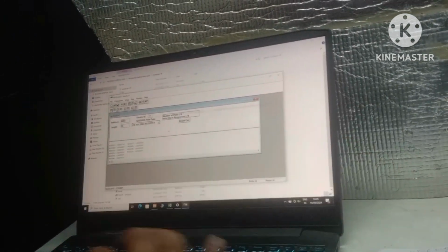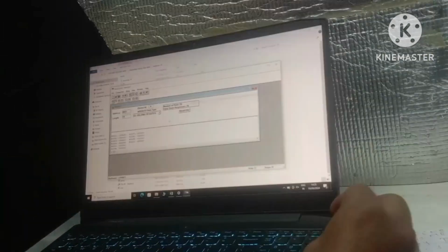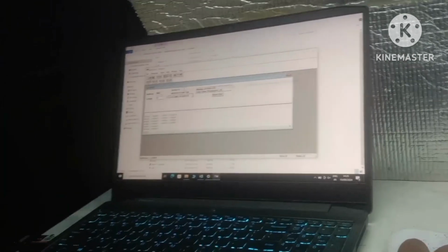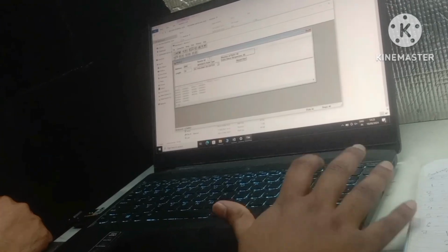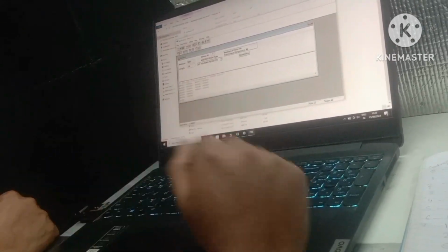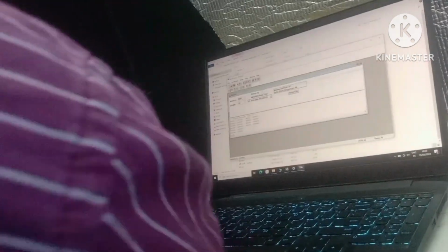If we have assigned a slave ID to that particular controller in the program, but physically, by mistake, we have given the wrong addressing, then we will not be able to communicate from the BMS system. Let's say I keep any of the other IDs here. If I kept 1, see, received invalid response. But if you keep 1 there, then I will be able to get that. I will keep 1.